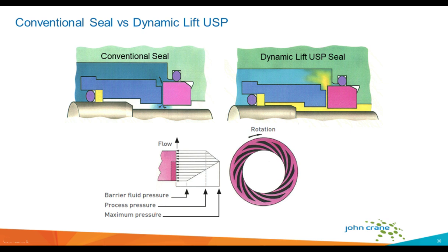The upstream pumping is so called because the principles are reversed, and we're now taking a chosen fluid and pumping it from the atmospheric side of the seal faces upstream to the higher pressure process fluid. Now, how that is accomplished is by utilizing the geometry of the groove and some basic fluid mechanics in terms of what happens when we try to compress a liquid.